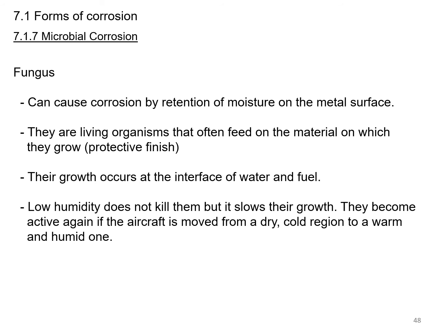Low humidity does not kill them, but slows their growth. They become active again if the aircraft is moved from a dry, cold region to a warmer and humid one. So aircraft flying up north are less susceptible to this. Aircraft that are flying in tropical conditions are more susceptible to that.